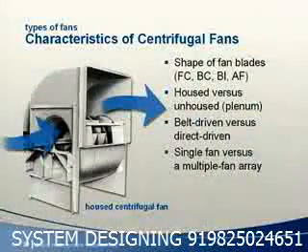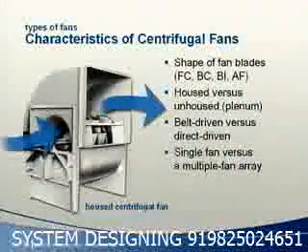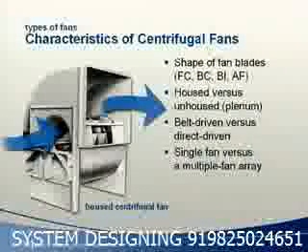Air handling units are typically available with several choices of fan types and sizes. This affords the opportunity to select a fan to best balance energy efficiency, acoustics, and cost. The most common type of fan used in an air handling unit is a centrifugal fan, in which air enters the center of the fan wheel and follows a radial path through it.